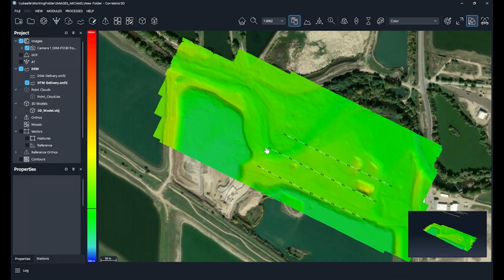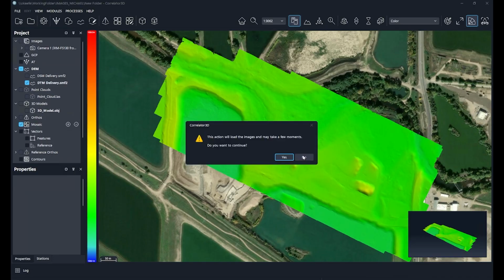Now, the next thing I'll point out is, if we go through the ortho rectification stage, can you have more than one ortho rectification folder? Absolutely. Can you have 16-bit and 8-bit? Of course. The only thing you need to do, after you finish ortho rectifying, let's say you did 16-bit, is go to the plus button and create another folder for your 16-bit. That's super simple. Simply create a new ortho folder, and it won't overwrite your run. Now, in this case, we also did our mosaic.